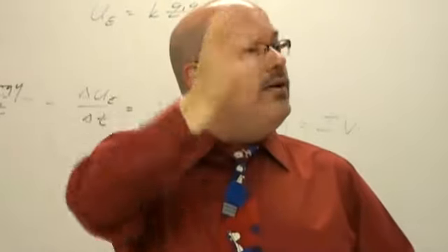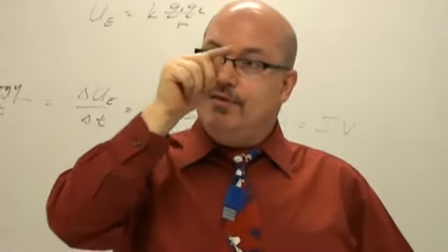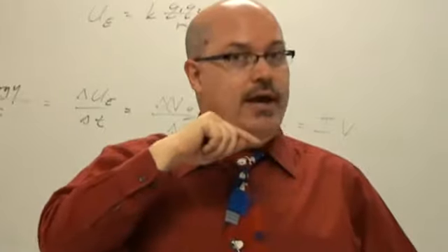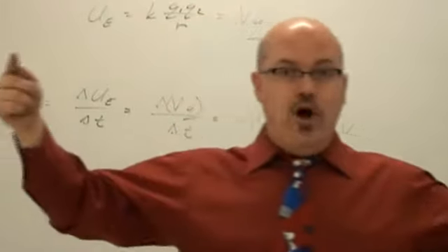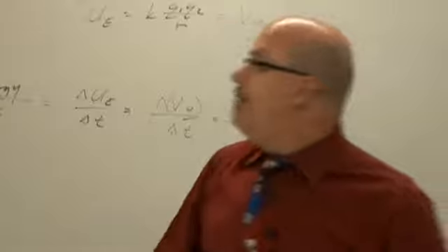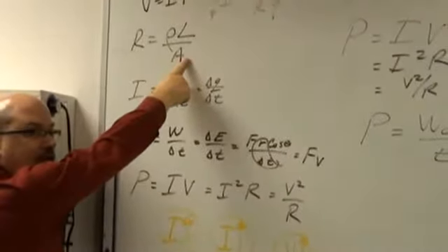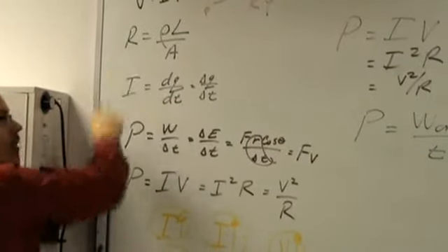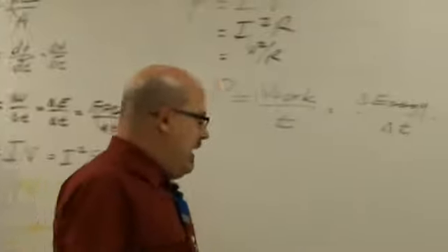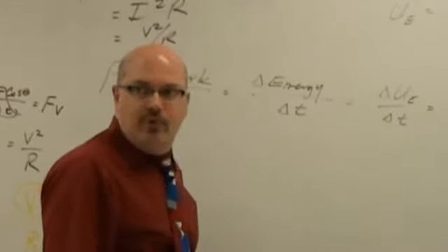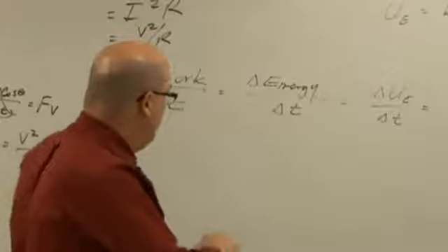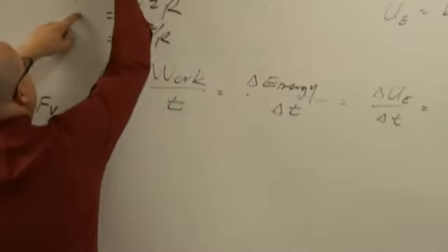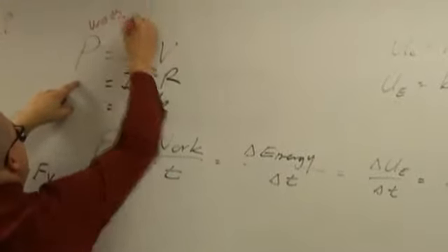But if you see a light bulb and you look inside a light bulb, one of those clear light bulbs, you'll see a little filament inside. It's a little bitty wire, okay? Little bitty wire that's pretty long, that's all coiled up, okay? So it's long and has a small cross-sectional area, so it has a high resistance, okay? All right? So what's the difference between a 40-watt bulb and a 100-watt bulb? Okay? Well, power is in units of watts still, right? Same as before.